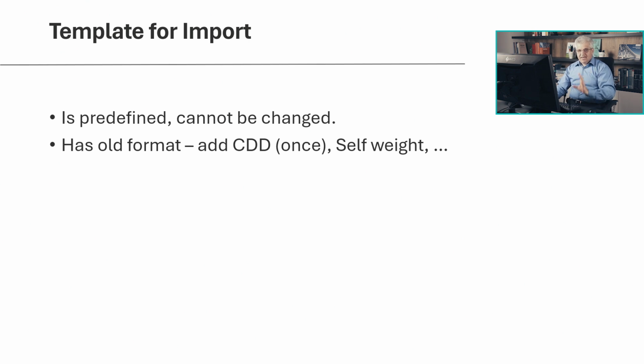If you import this IFC, sometimes I get a question, can I select some template for the import where I have, for example, layers or load cases already saved? Not, this is not possible. The IFC import is using predefined template. You cannot change it.